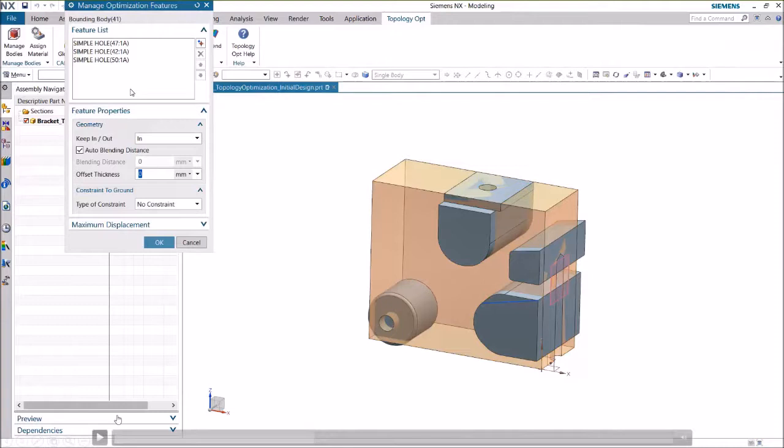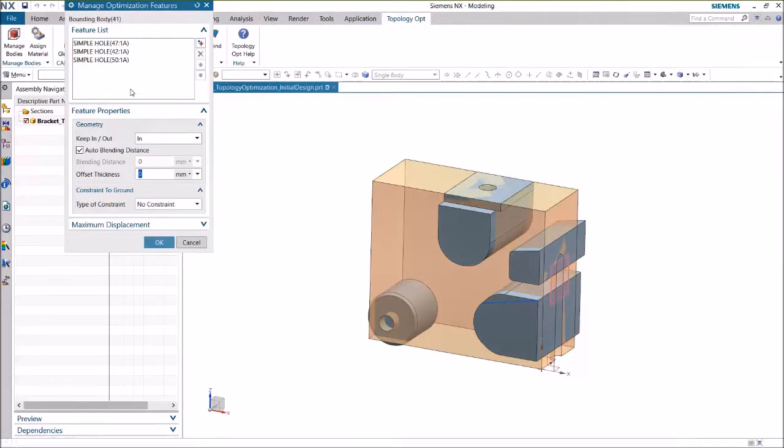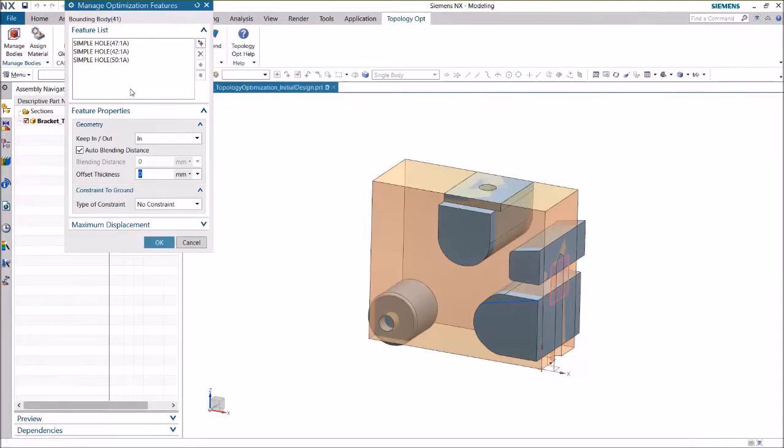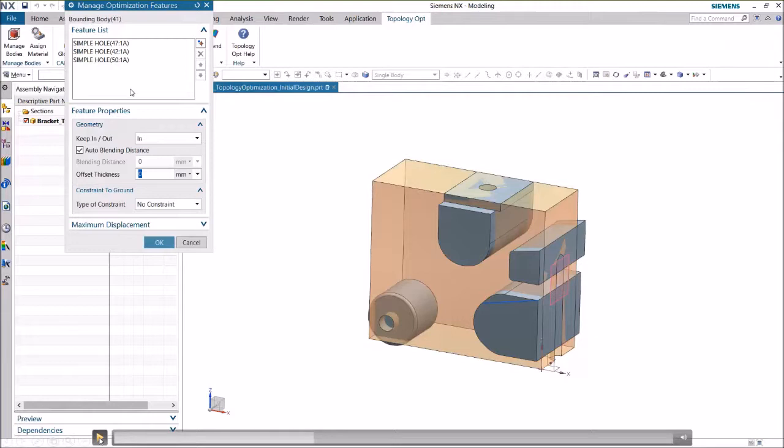And also you can define so-called manufacturing restraints, like for extrusions, where you have a construction in a certain direction, or towards additive manufacturing. You can also define a maximum overhang angle towards a certain direction and so on. All these things you will define directly there using these CAD features.